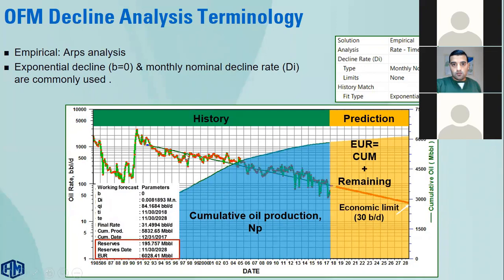So in OFM on the decline curve analysis, we will match the past performance, as you can see, using this straight line, using the exponential approach to predict the future production and get the estimated ultimate recovery, EUR.